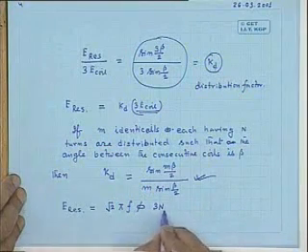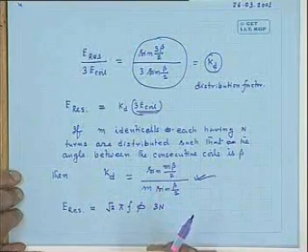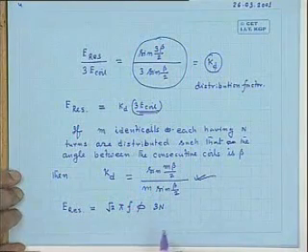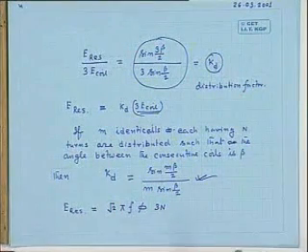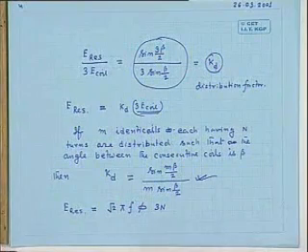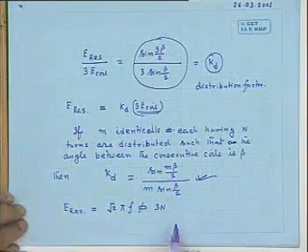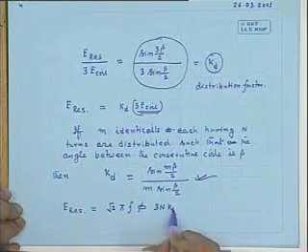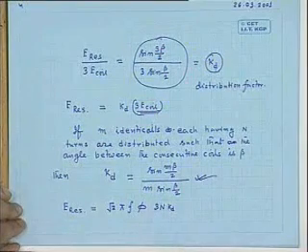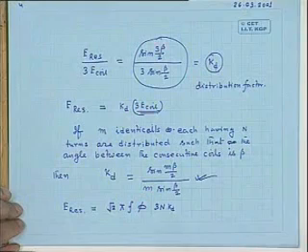If I write only 3n, shall I be wrong or correct? For distributed coils, this would have been 3n, provided all the coils were concentrated in the same pair of slots. Now you have to multiply with Kd. That is, by this factor induced voltage gets reduced.